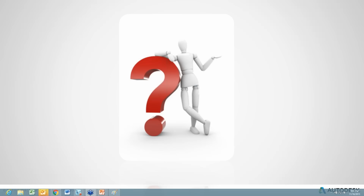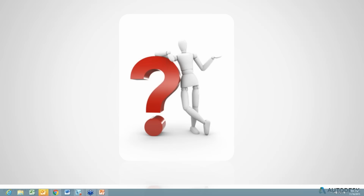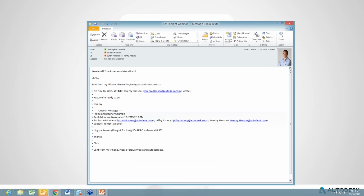One other thing you might see with .NET is if you're trying to install on Windows 10, or if you've installed .NET 4.6 on Windows 7 or Windows 8, with certain Autodesk products, you'll get an error saying that .NET 4.5 is not installed. The reason for that is the installer is looking for either .NET 4.5 or newer, and its definition of newer is 4.5 point something.